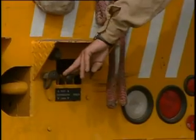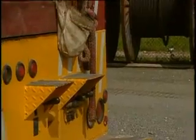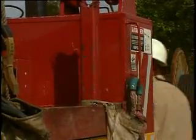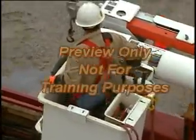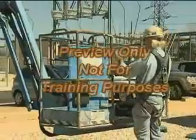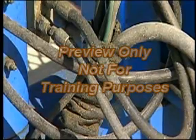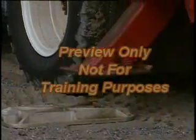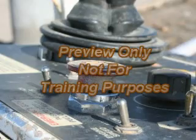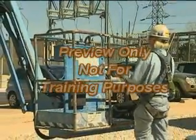Controls should never be forced from one position to another. Always inspect the boom for damage and/or any signs of weakness. If the lift is insulated, make sure it is dry and free of grease or oil. Check the guardrails. They should be free of damage and at the proper heights. Check the hydraulic system for possible leaks and the fluid level for proper amount of fluid. Outriggers should work properly and should always be set. Emergency stop buttons should work correctly. Tires must be properly inflated and inspected for damage. All safety guards should be checked for malfunctions.